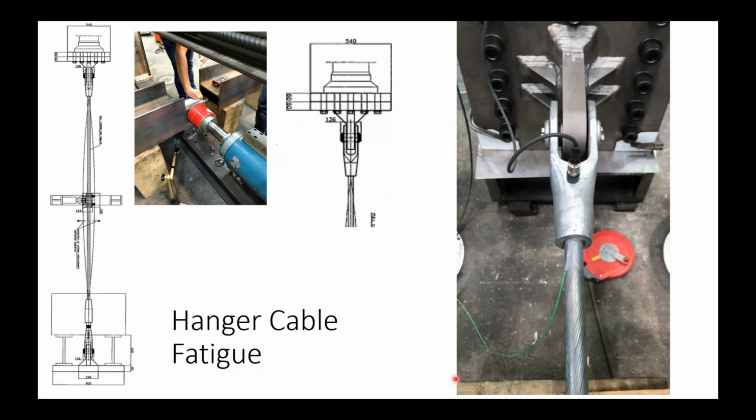But the testing criteria that we developed: on most highway bridges or railroad bridges, the fatigue test on these elements really comes from either a truck tire or a railroad axle passing the location of a stay, creating an axial load spike in the stay, and as axles pass, then it gives a cyclic axial load. Well, in this bridge, in a pedestrian bridge, really the pedestrians don't generate that much of an axial load cycle in the bridge. There is a little bit, but it's not as significant on say a freight train bridge.